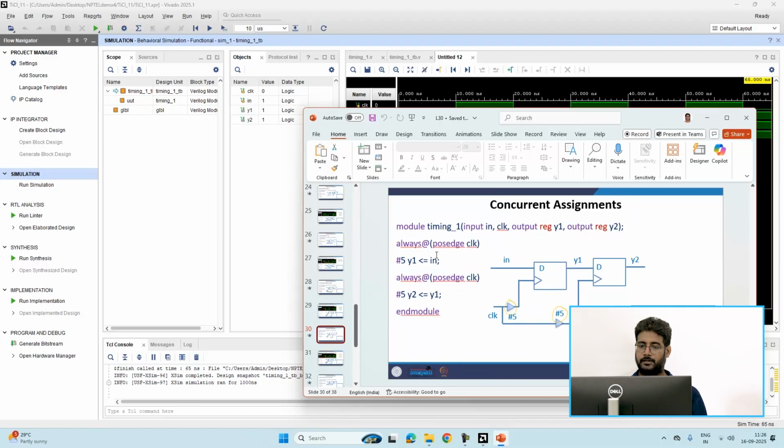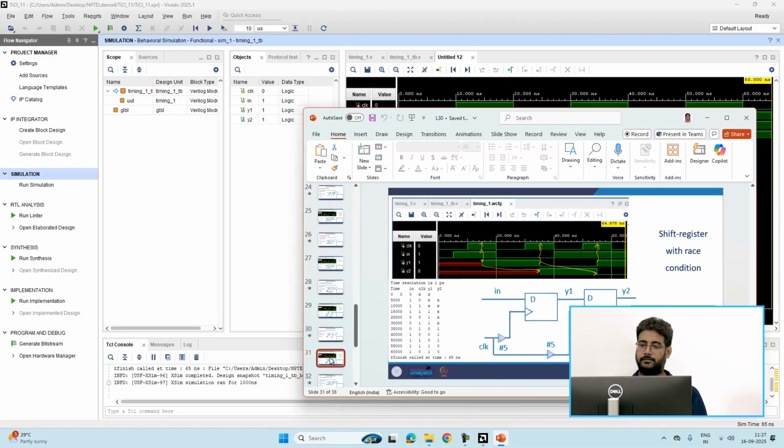So here at the positive edge of clock, it's similar, but evaluation will happen, but execution, the assignment, is delayed. There is no statement after it. So it is again similar to the previous case. It's a 5 clock cycle delay for this and a 5 clock cycle delay for this, because in this always block there is just one statement. So even if evaluation assignment is delayed, it doesn't matter. Okay, so it is like the previous case only. So the output is this.